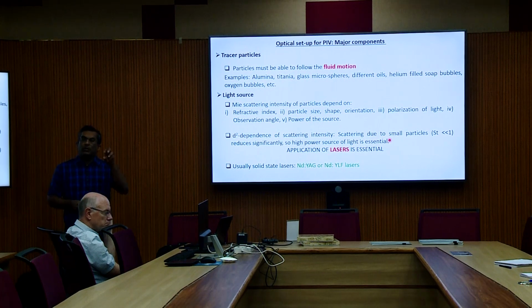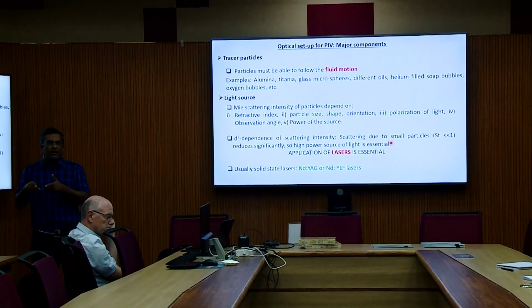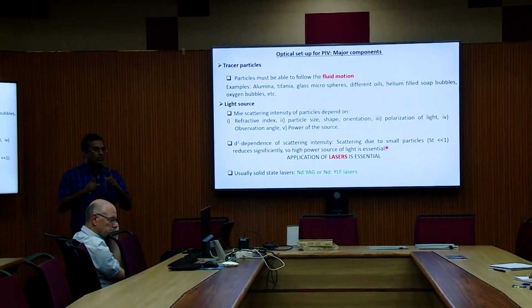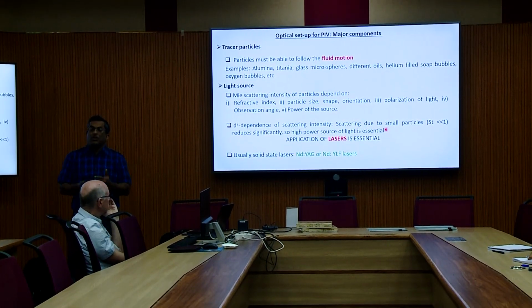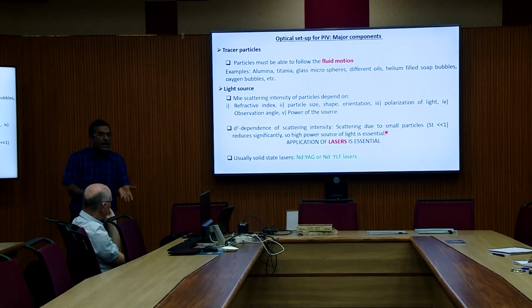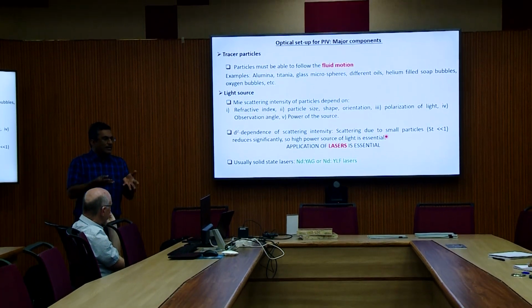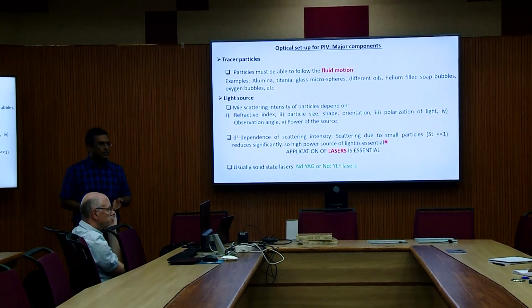However, in order to calculate Stokes number, you need the information on the turbulent time scale. But your intention is to measure the time scale of turbulence or to characterize the turbulence. So how would you know beforehand the time scale of turbulence such that you can calculate Stokes number? I hope it is clear to you.